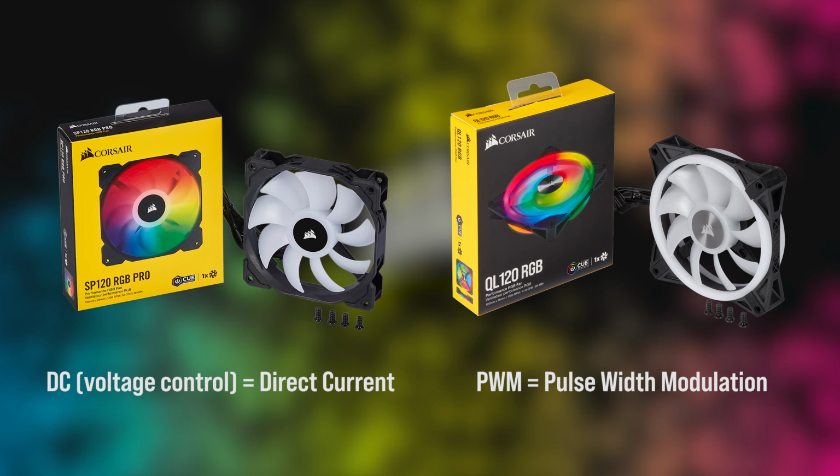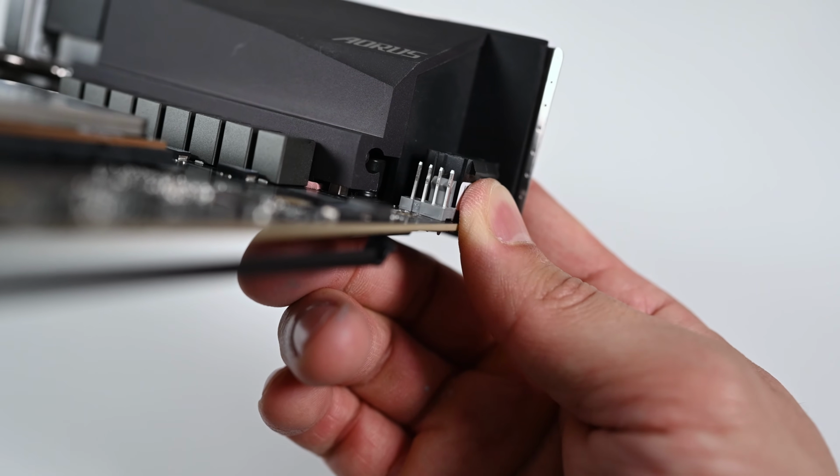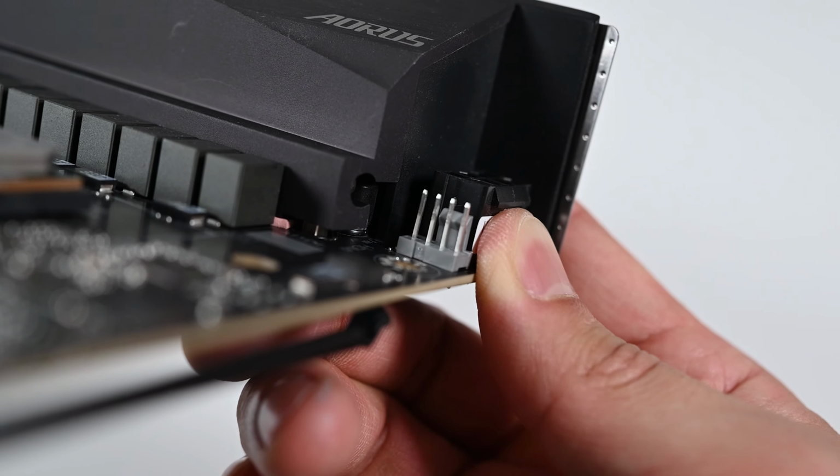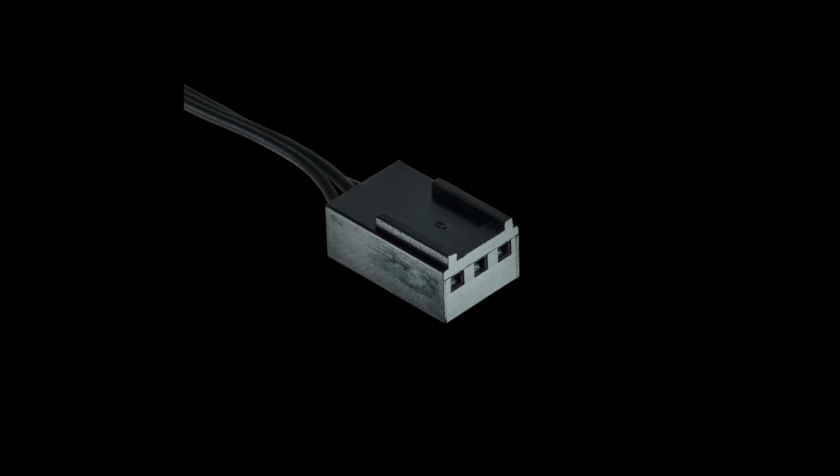For DC case fans, a header or controller will feed a certain amount of voltage to your fans, usually between 12 volts or 5 volts, with 0 volts being off. A standard DC fan can be recognized by the common 3-pin fan connector.